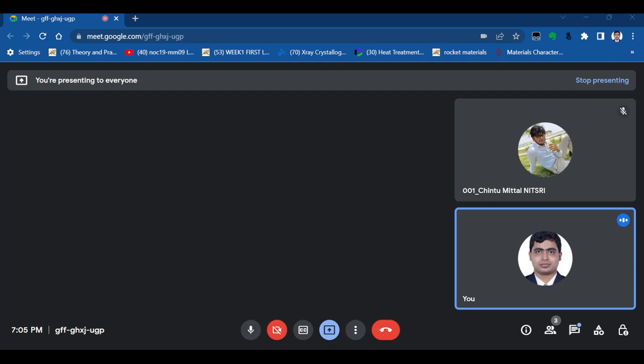This is same for both cases. This is also same. So if this is larger for X, then this A should also be larger. So material X can withstand larger flaw size. Alloy X. So this one component made from alloy X can tolerate a larger flaw size compared to that made from Y. This will be the right answer.